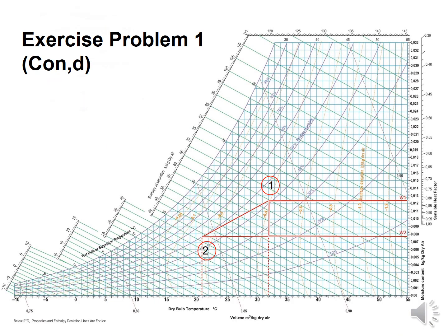So this is a psychrometric chart where point number 1 and point number 2, the state points, have been drawn, and the process line. In this question we need only the value of humidity ratio W1 and W2, and we can see that against the points 1 and 2 on the vertical axis we have calculated the values of W1 and W2.